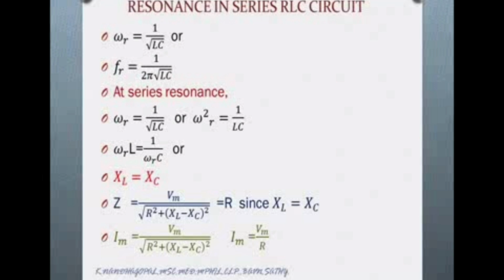When you are varying the capacitance value, at a particular value, the capacitive reactance is equal to the inductive reactance. This term becomes 0. That current flow is maximum, so you can hear the sound.